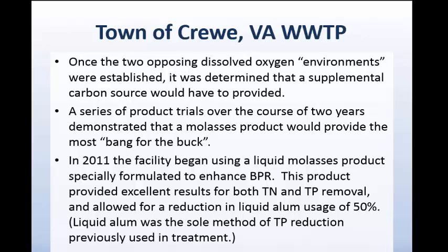They actually even brought us in a tank, a pump, and the product, and the product provided excellent results for both total nitrogen and total phosphorus removal. The total phosphorus removal was really unexpected, and the best unexpected part was getting the biological phosphorus removal, when previously the only means of phosphorus removal we used was chemical. We used liquid alum. Being able to lower our liquid alum usage by 50% enabled us to realize a significant cost savings when it came to the phosphorus removal.